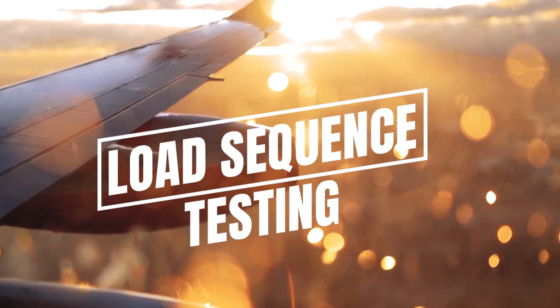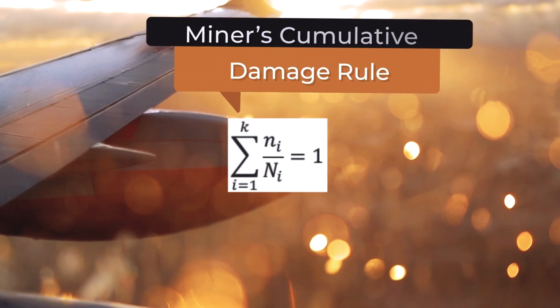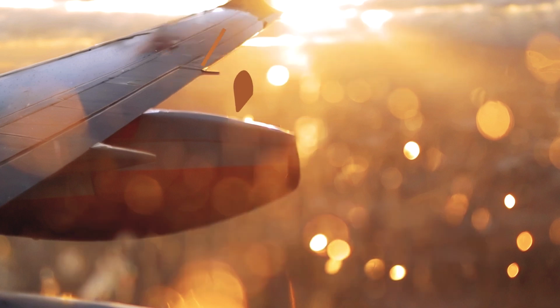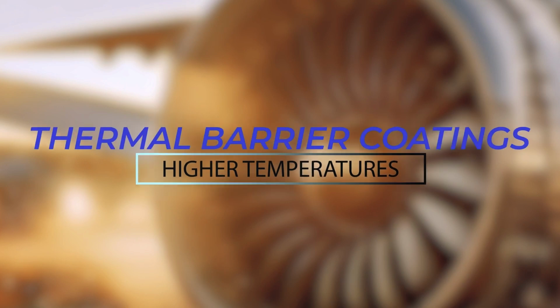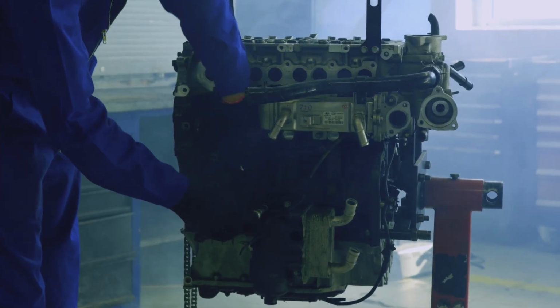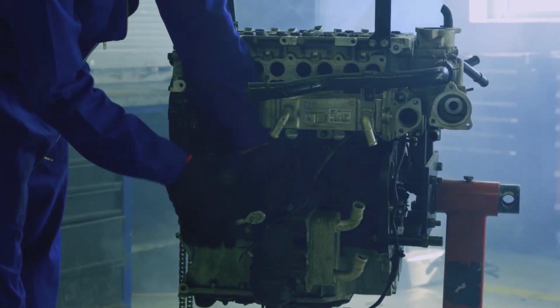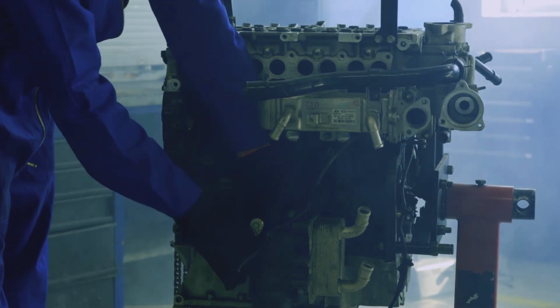For aircraft wings, load sequence testing provides data for fatigue analysis using Miner's cumulative damage rule. This helps determine inspection intervals to detect cracks before reaching critical size. In jet engines, thermal barrier coatings allow higher operating temperature, reducing thermal fatigue. In automotive powertrains, fatigue testing of prototypes ensures durability of components like piston rods, which undergo billions of tension compression cycles over vehicle lifetime.